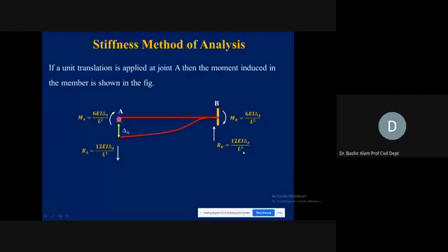This is how we get this 12 EI delta, and this is how we get its sign also. It was in the clockwise direction, so the balancing couple is going to be in the counterclockwise direction. So we found all the member end actions because of this settlement. We found all the member end actions because of the rotation also, if it is given at an end. Any questions?